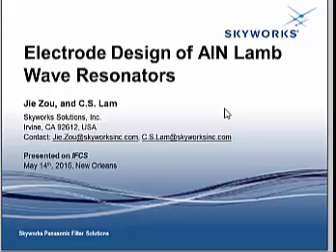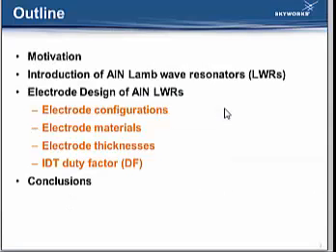I'm from Skyworks Solutions. Today I will talk about the electrode design of aluminum nitride Lamb wave resonators. This is a theoretical study for research purposes. Here is the outline: the motivation, an introduction to aluminum nitride Lamb wave resonators, and then four considerations on the electrode design, including the impact of electrode configurations, electrode materials, electrode thicknesses, and IDT duty factor.